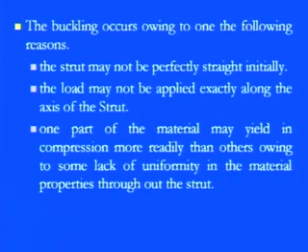So this is known as the material nonlinearity. It means that if the material is not isotropic, if the material is not behaving perfectly and uniformly all along the length of the strut, then obviously when we are applying the load, at some part we have more distortion, more deformation as compared to the other part, and due to that we have a great chance of failure because of this material nonlinearity, because there is no uniform transformation of the material.